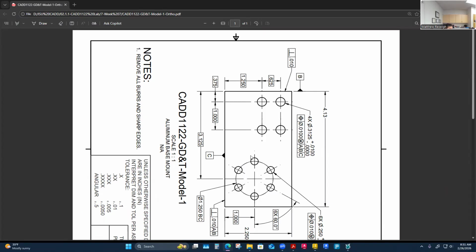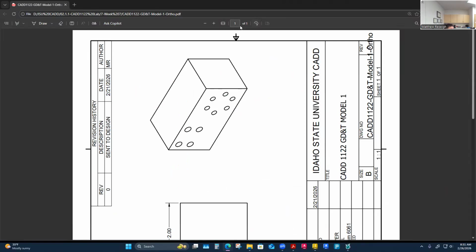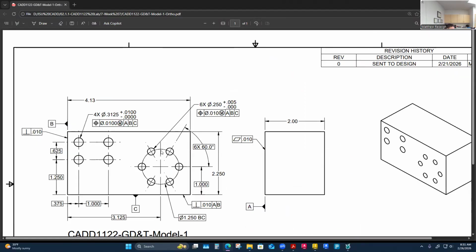They could definitely put their two-hole pins and then level it across this way, do a vertical leveling between the 6 o'clock and 12 o'clock hole. And that would tell them that they're straight up and down, but the problem is they've got to hold that unless it's a magnet or something. This allows, if I'm two-holing a hole pattern like this, even with non-magnetic, non-ferrous materials, I can still set a level across there and level these up. So that's just a concept, and it plays out for a lot of hole patterns in general. So this is what I would call a two-hole pattern, but it's obviously on a bolt circle. So free information there. Excellent.